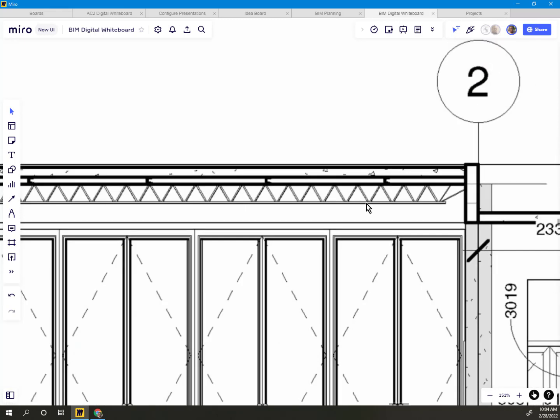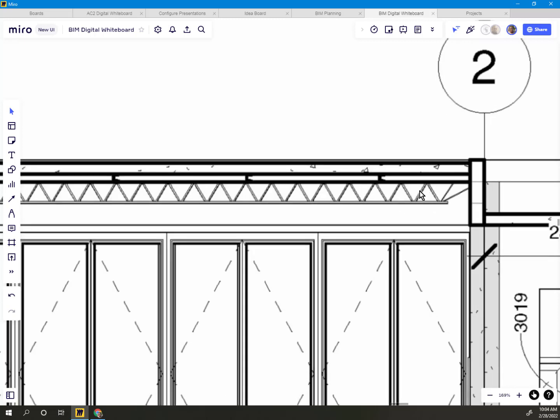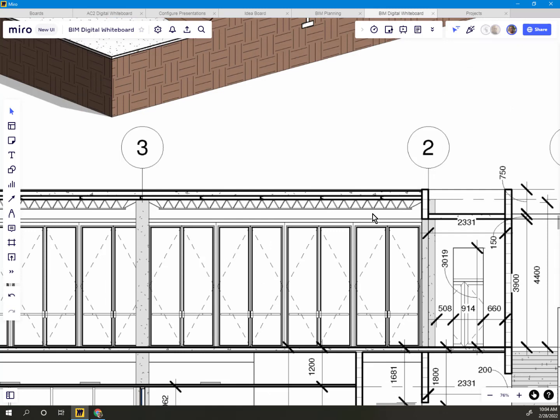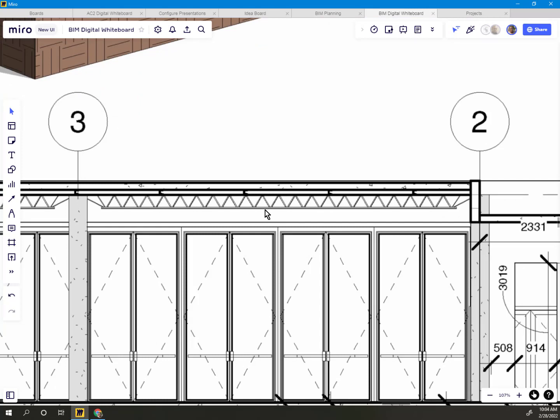So sometimes what we do at the architectural stage is a little bit representational, because some things will get modified by the engineer anyway. So you don't need to invest in modeling out a full beam system, because it's just not your area of focus, but you do still need to represent the beam system here. And this is how BIM is supposed to shine, because the engineer can open your BIM model, and that engineer, who cares about the beam system, can now go in and modify the beam that you created with the precise beam that should be used. You guys following me? You understand what I mean?